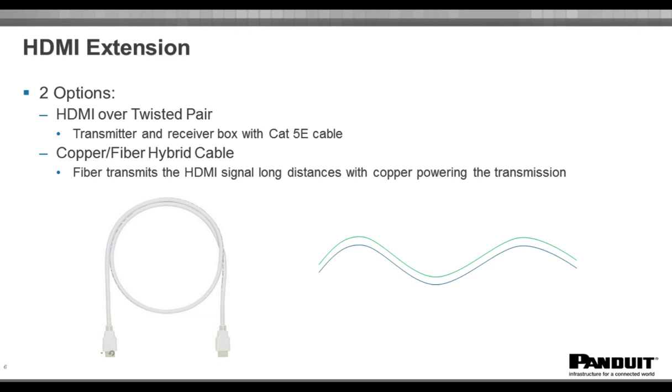So HDMI, when you take a native HDMI cable, it can reliably only go about 15 feet, depending on the quality of your patch cord. Whenever you're looking at purchasing a standard HDMI patch cord, make sure you check the bag or the box for a certified premium HDMI 2.0 sticker.